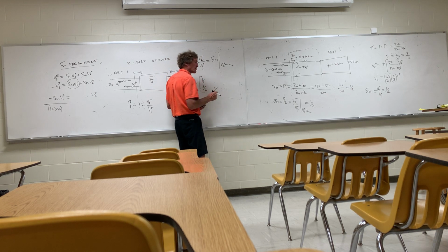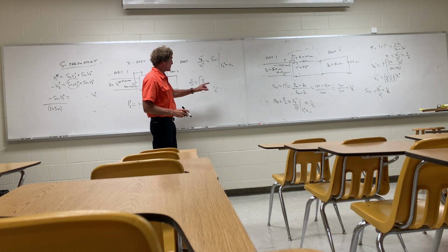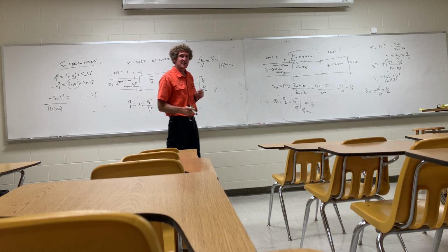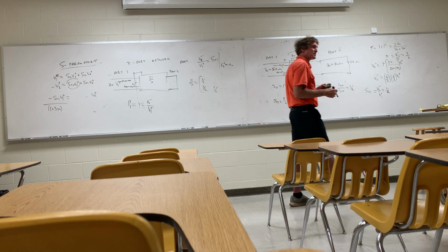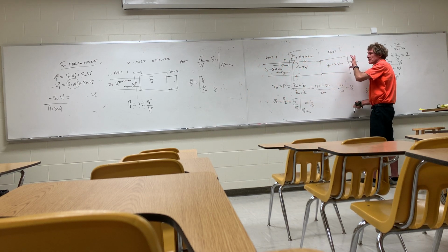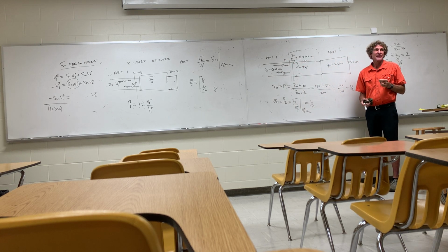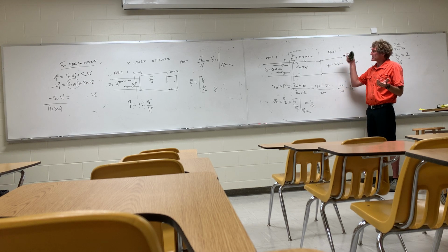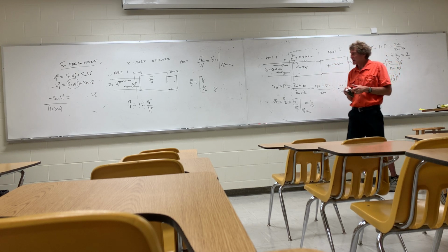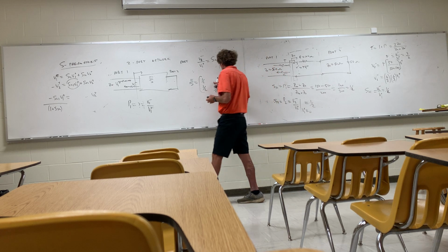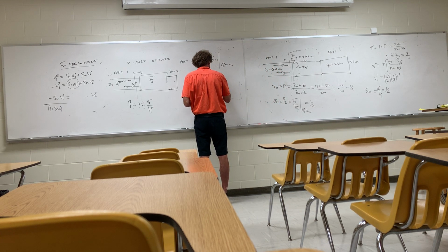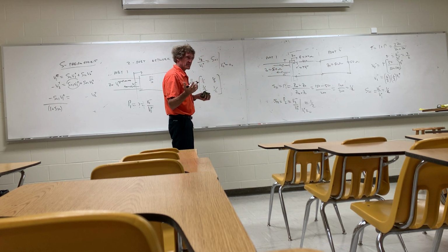This is an interesting network. Anybody want to take a guess what the reverse gain is? The reverse voltage gain? In other words, if I put a voltage V2 plus here, how much V1 minus comes out? You're right. It's a symmetric network. Can you all see that, class? It looks exactly the same either way you look at it. So this would be 1/2 also. This is a problem out of this book. It just gets you started. Everything's 1/2 there, but it's the beginnings of your understanding of S parameters.